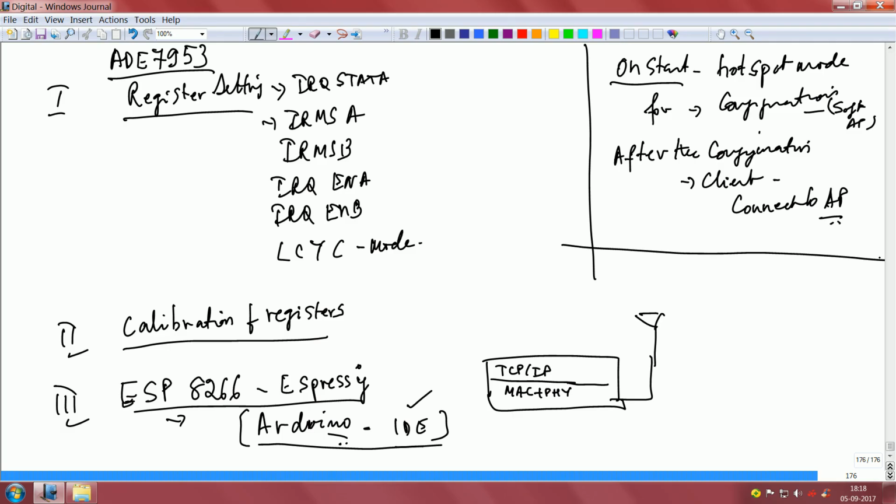Now there is something interesting that we have configured in this chip, trying to use its power. If you cold start the Joule Jotter, I mentioned to you that we need an Android app for configuring several parameters, right, and that essentially means you are in the soft AP mode. The ESP module is put into soft AP mode, and users can type in the parameters of interest like device names, sampling rate, and all that. You can use this ESP in the hotspot soft AP mode.